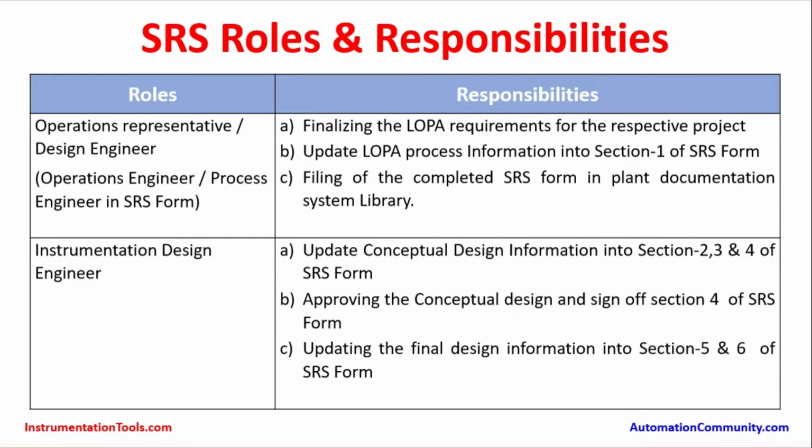And the instrumentation design engineer, he has to update conceptual design information into sections 2, 3 and 4 of the SRS form, approve the conceptual design and sign off section 4 of the SRS form, and update the final design information into sections 5 and 6 of the SRS form. These are the three different responsibilities that the instrumentation design engineer has to follow.